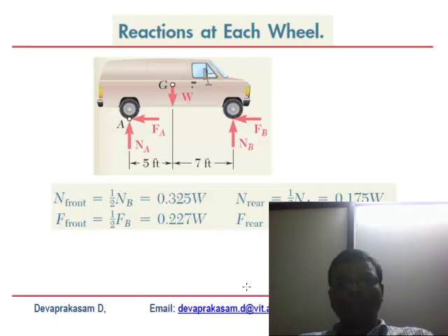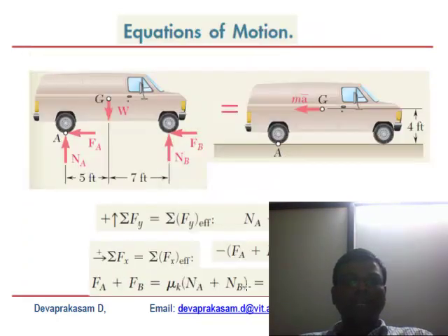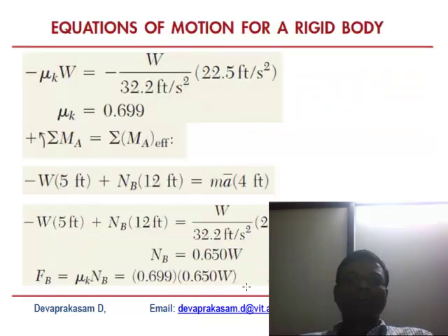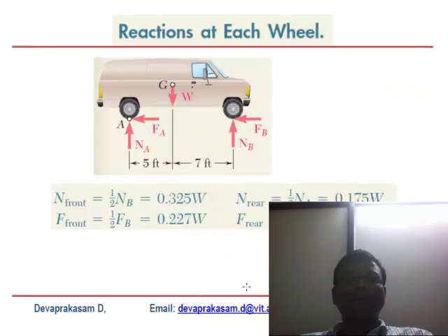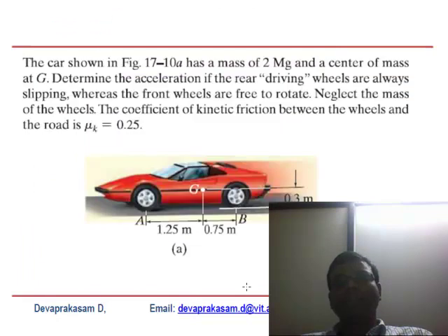So let me again emphasize that as soon as you have the problem, you have to draw a free body diagram, resolve these forces in the x and y direction, and take the moment if there is an unknown component. From that we can converge very quickly to what is needed. So now we see the second problem.